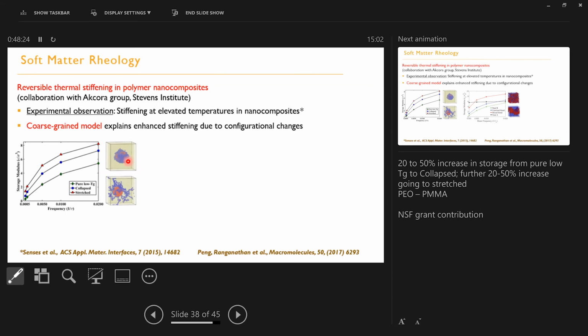Okay, the high stiffness chains are collapsed on the nanoparticle, and the second configuration is what is called the stretched configuration. Okay, so imagine you heat up this nanocomposite. The blue polymer chains have enough kinetic energy to stretch out, right, and experience the configuration with this. Let's say you have these two configurations, okay, and we again subjected this to the oscillatory deformation, and this time